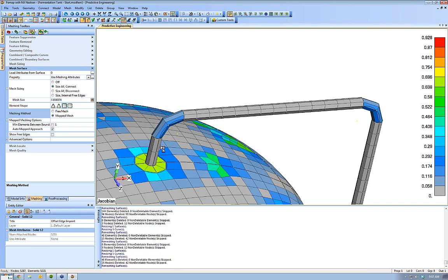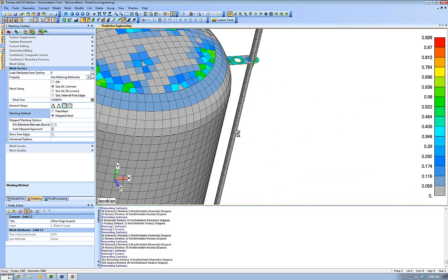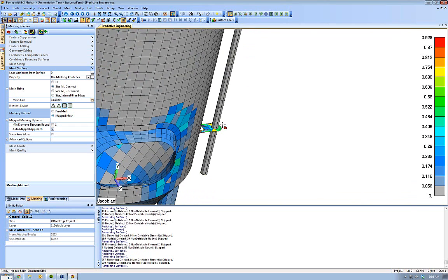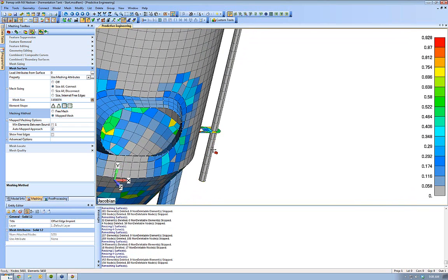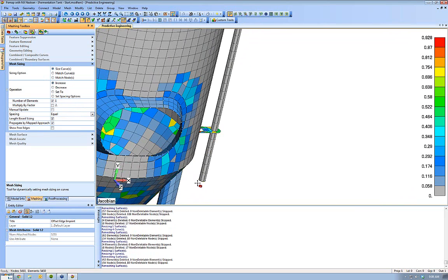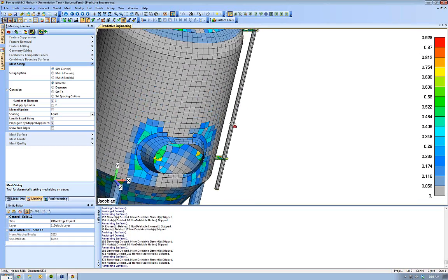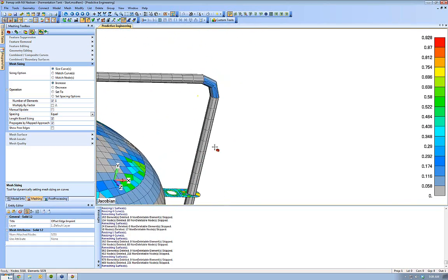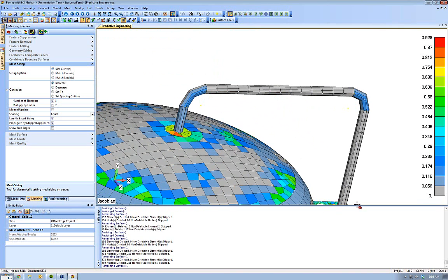And we'll get to the point where the whole thing will be mapped, and we can pick our mesh sizing at one end, and it'll propagate through the rest of the pipe. So let's try that. We'll go to mesh sizing. We're going to increase by 1. We're going to increase this one here. And as I do this, it propagates up to the next surface, all the way through. Since all of these surfaces are mapped and they're all adjacent, that mesh size is going to propagate its way through and update the entire pipe.